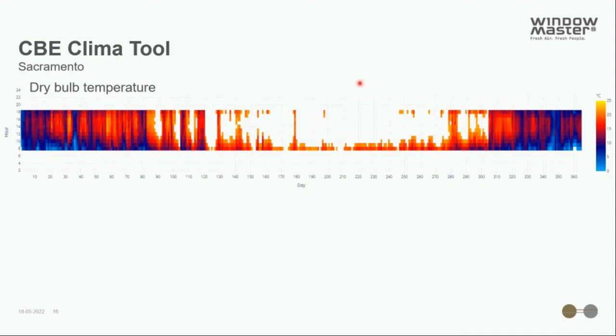our building, which in this case was 0.4 cubic feet per minute per square foot. So all the hours here, it will comply, and in the summertime, it will not comply based on the temperature difference. And as we also have to consider thermal comfort, this seems very reasonable. Now, if we wanted to, we know our design, because we have openings on different facade orientation, we know that our design also allows for